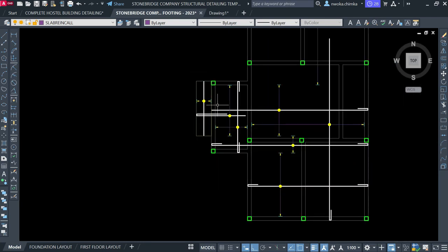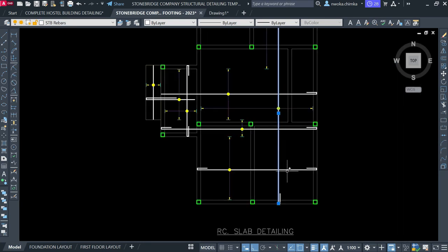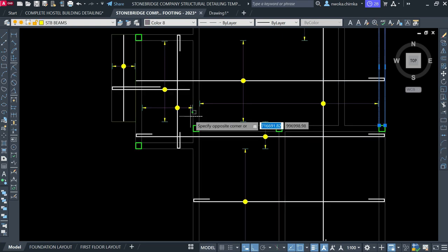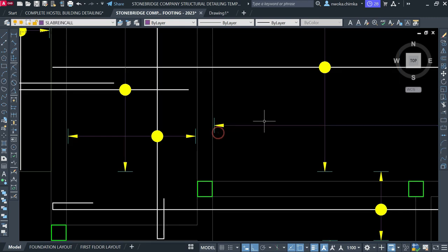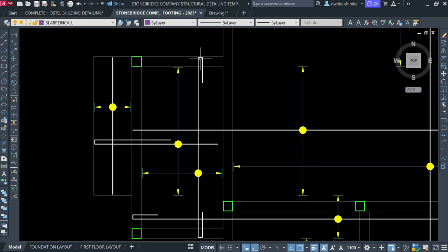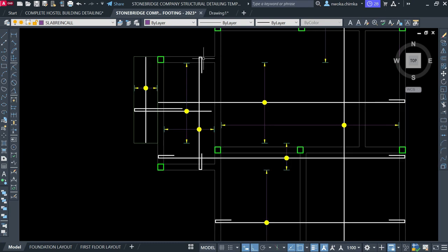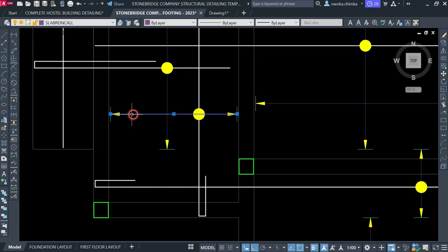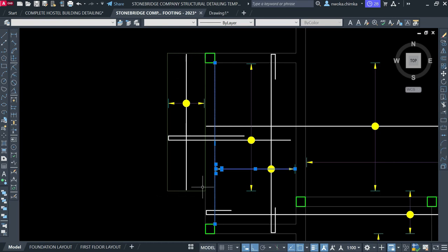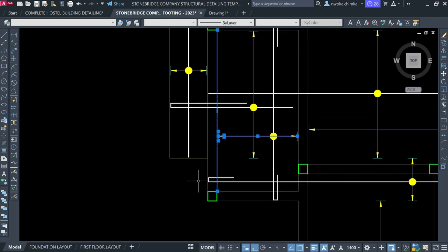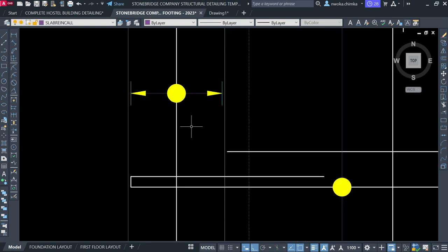Okay, so now these bars run all the way from this point of beam to this point of beam, because they have the same shape here. Now trying to pass this shape, it finds that there is a different smaller panel here. It has to stop on this very point. Another bar then continues, which will fit into this panel, continues bend and bend, and then runs from this very point to this very point, and now stops because there's a change of shape of the cantilever, which is here, and this place doesn't have anything, so it has to stop here, and then this bar continues.